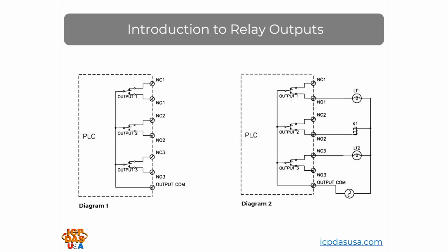Coil K1 would have to be rated for AC use, in these cases at the voltage available from the AC power source. The wiring of these outputs is similar to a switch controlling a light bulb. A normally closed switch or a normally open switch could be used. A switch placed in series with the light bulb and the power source would control current to the light.